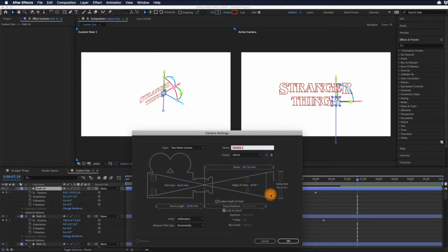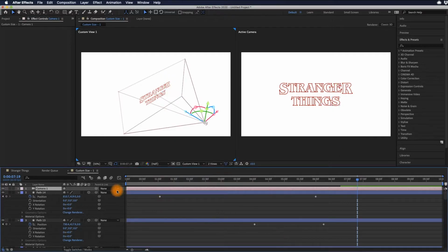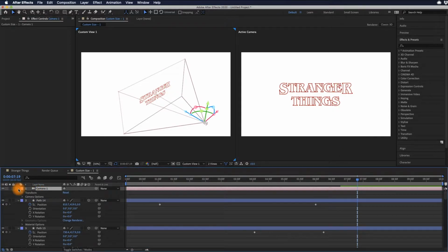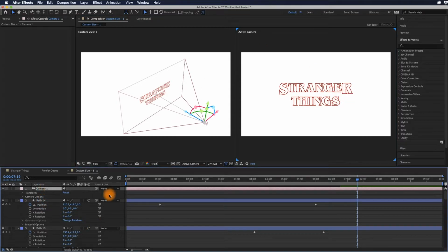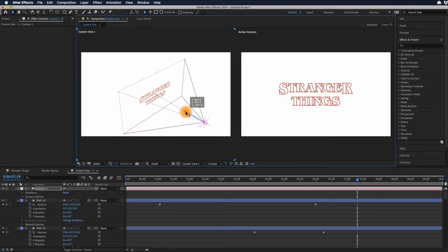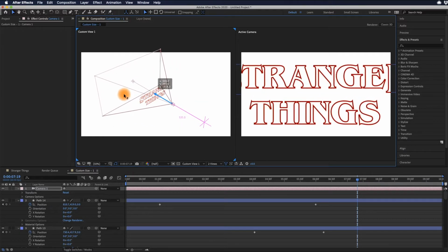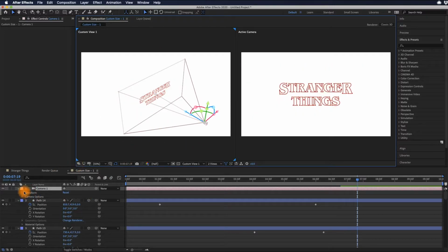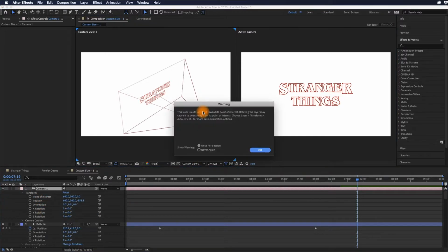Okay, so then we can go to the layer, create a new camera, and you can use camera 24 millimeters to create a camera. So by default they have a camera, but you don't have control. Once you add your own camera, then you can have some new controls with it. Okay, so for example, with the camera you can zoom in, zoom out, you can fly through this object, and you can tilt and bank. You can just change it. It's like you hold a camera.